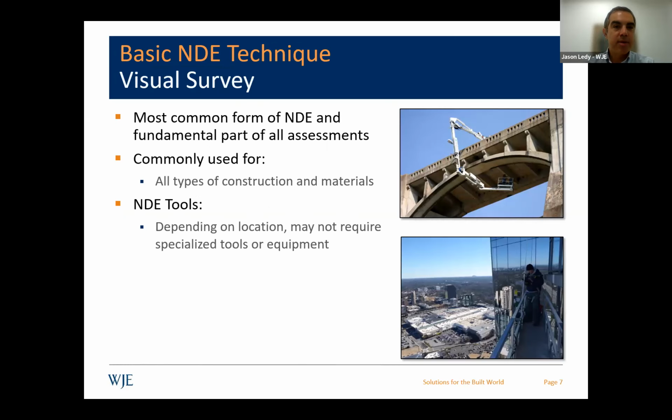The most common NDE technique, which often is not thought of as NDE, is a visual survey. There are various forms of completing visual surveys of structures, and a lot of it depends on the access to the structure. If it's a tall building, it may involve suspended scaffolding, pipe scaffolding, aerial lifts, or rope access as another option.